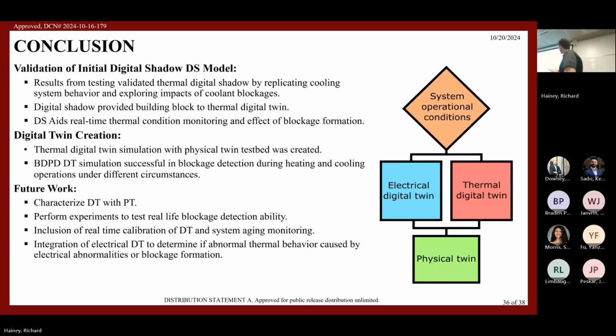So what I've talked about here is basically the building blocks of building a system that can detect blockages within a water-cooled power electronic system. Now, there's still plenty of work to be done. With this, we need to incorporate an automatic recalibration feature for our model, perhaps incorporating particle swarm optimization that can update or recalibrate our digital twin system to maintain accuracy with our physical system.